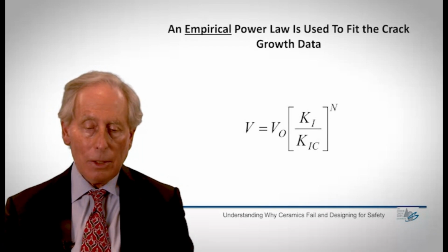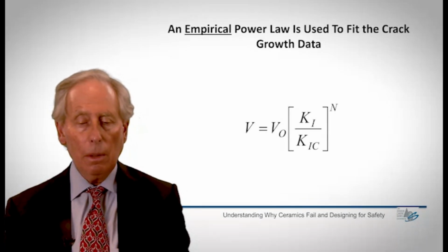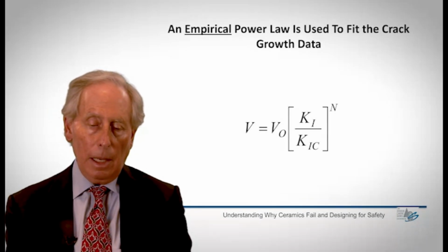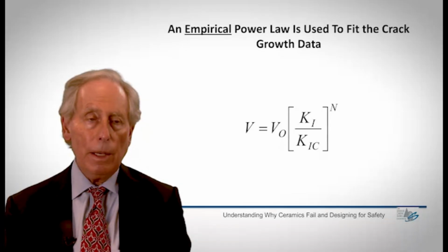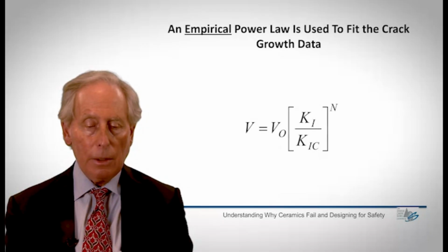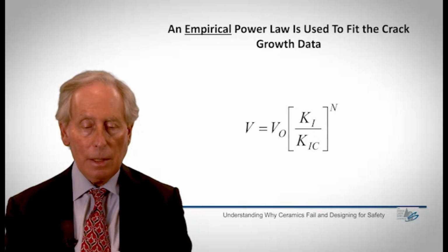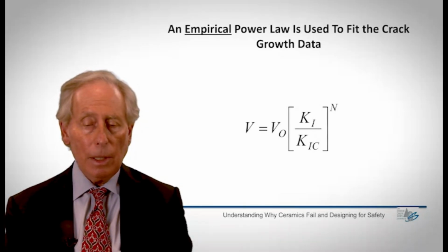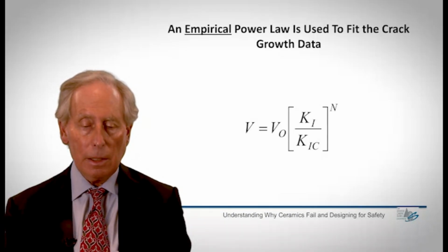So let's go back to the fact that cracks grow with time. I showed earlier in section 2 that we used a log function to describe the crack velocity as a function of stress intensity factor, but that doesn't work very well for various reasons in the engineering analysis of crack growth.